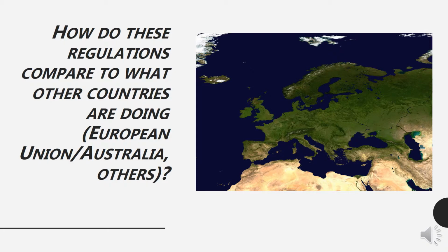Overall, international regulations for DBPs are very similar to maximum contaminant levels under the Stage 1 and Stage 2 DBPR in the U.S. For example, in the U.S., the maximum contaminant level for total THMs is 0.08 milligrams per liter, and guidelines for Europe, Canada, China, and Japan have been analogously set at 0.1 milligrams per liter for total trihalomethanes. U.S. regulations for bromate and chlorite also compare to regulations in China and Canada, but there is greater variation in the regulation of